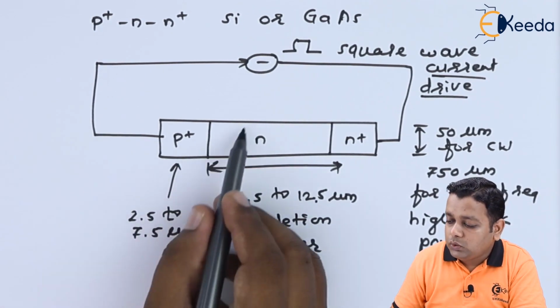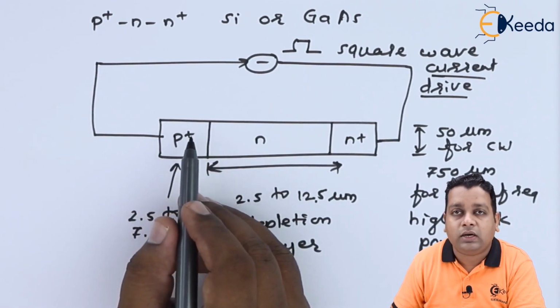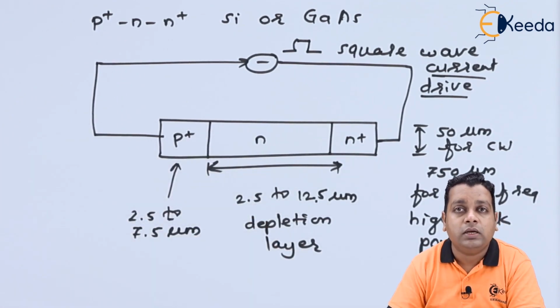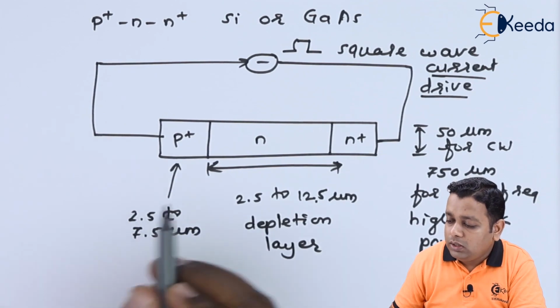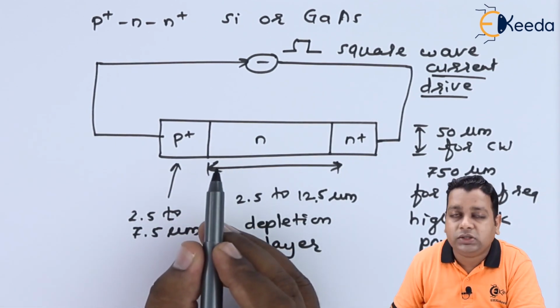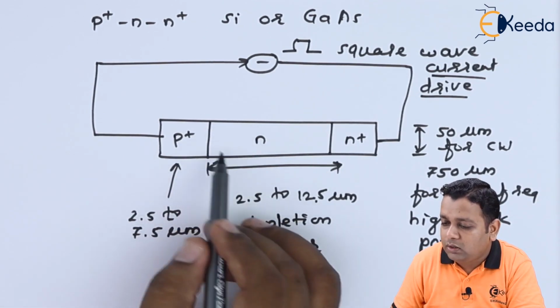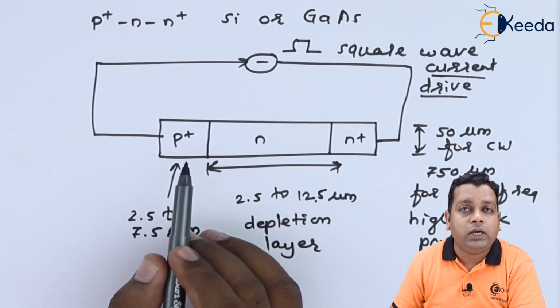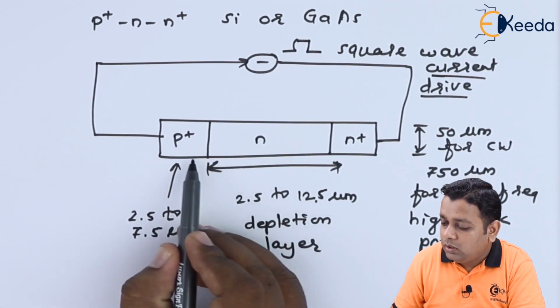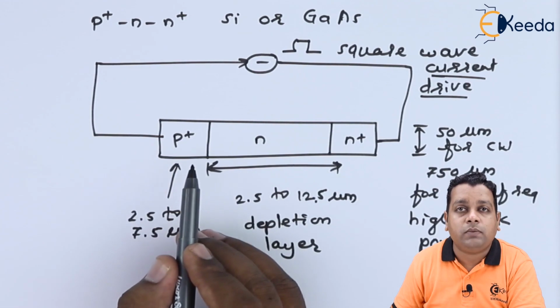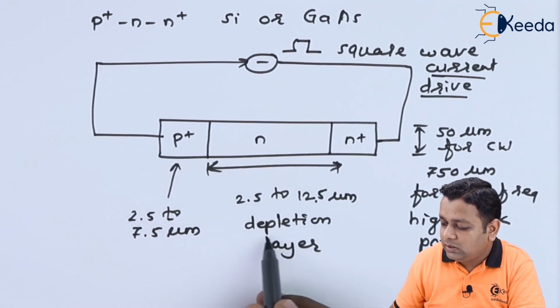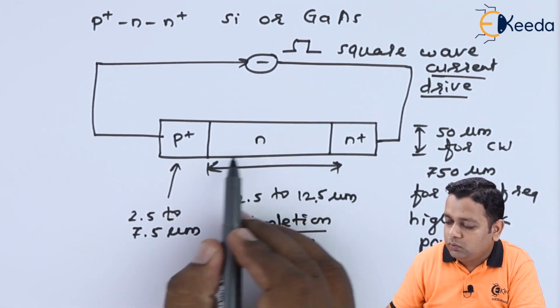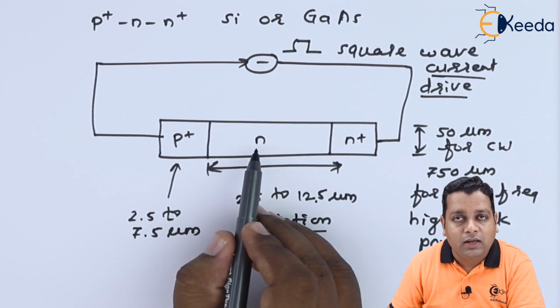Further, because of the reverse bias, there will be high field domain generation. So the high field avalanche region that will be developed here in the N-type material will propagate through the diode body, and it will fill the depletion layer. See, the depletion layer we have shown covers the entire N region.